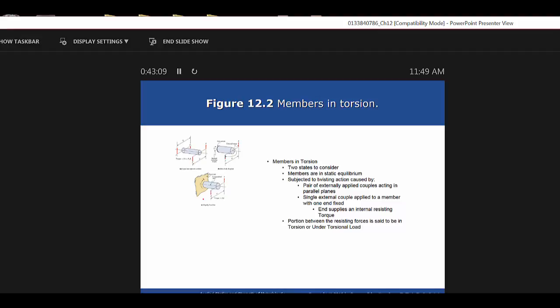Okay. So if we look at that, again, note that that's strictly pure shear stress. There's nothing pulling that shaft or compressing that shaft. It's strictly torque, if you will, from that perspective. It's pure shear stress, with no bending or direct tension or compression. The internal resistance to the slippage of the material or the deformation is known as torsional shear stress.